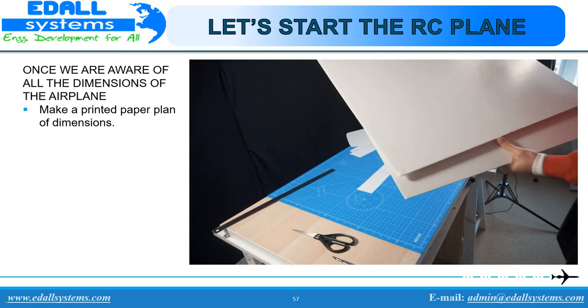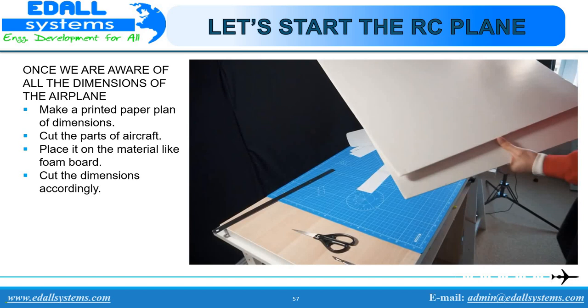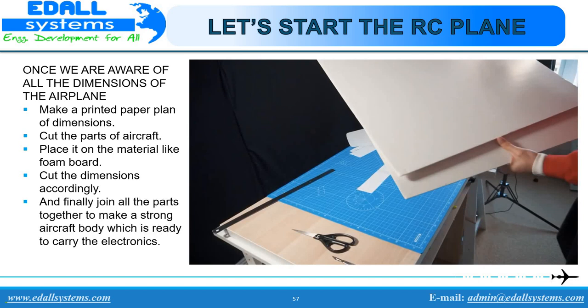Make a printed paper plan of all the dimensions. Cut the parts of the aircraft. Place them on the material like a foam board. Cut the dimensions accordingly. And finally join all parts together to make a strong aircraft body which is ready to carry electronics. Now we are done with the calculation and construction part of the RC model. Let us move on to the electronic construction of the RC model in the next session.